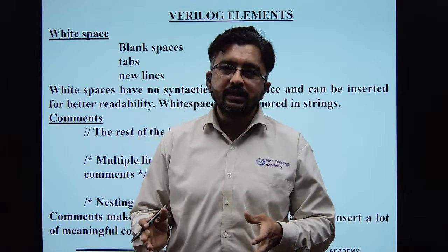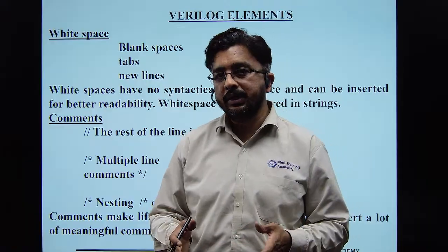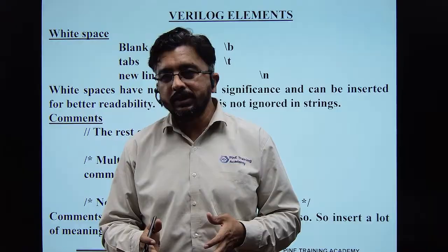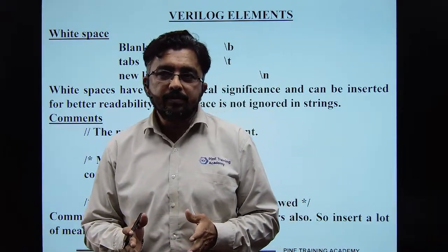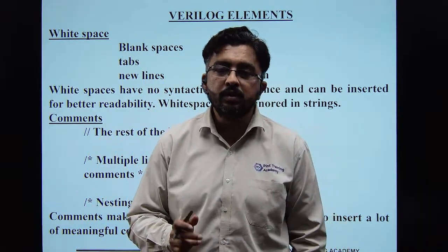Something is common, I can say 70-80% of the syntax is common, which we call synthesizable constructs. There are two types: synthesizable and non-synthesizable. Non-synthesizable syntax is used for simulation purposes, not for generation of your netlist.